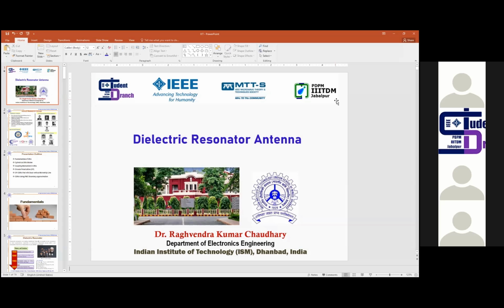You may have other arrangements for getting higher gains, like using artificial magnetic conductors, or you can use an FSS. The best thing is to use the starting 4 or 5 modes, so you can predict the radiation pattern very easily. With a very high order mode, the radiation pattern is very irregular and may not be used for medical applications, so we need to see these things.